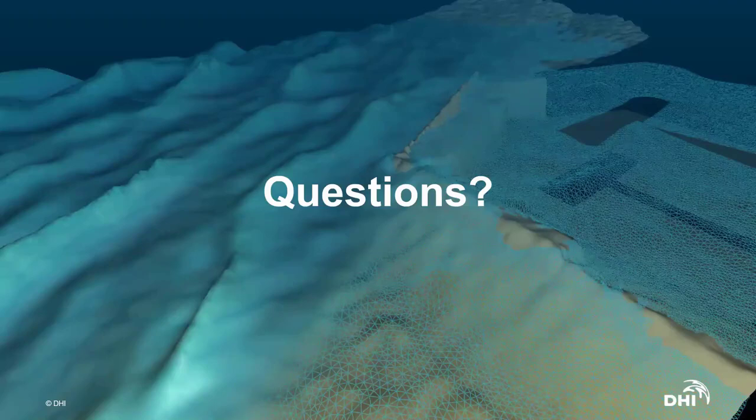All right, so Philip Van Loon asks, we have tried to set up a wave modeling overtopping case with a 3D DFSU porosity map, and we experienced it was quite difficult. We have received the following workaround: to make a dummy Mike 3 HD FM setup with the method that you plan to use in the Mike 21 Wave FM setup. Run the Mike 3 HD FM for one time step and save a dummy 3D DFSU saving temperature, for an example. You can then manually edit the 3D DFSU you saved with the porosity values you wish to use. Then this can be used in Mike 3 Wave.